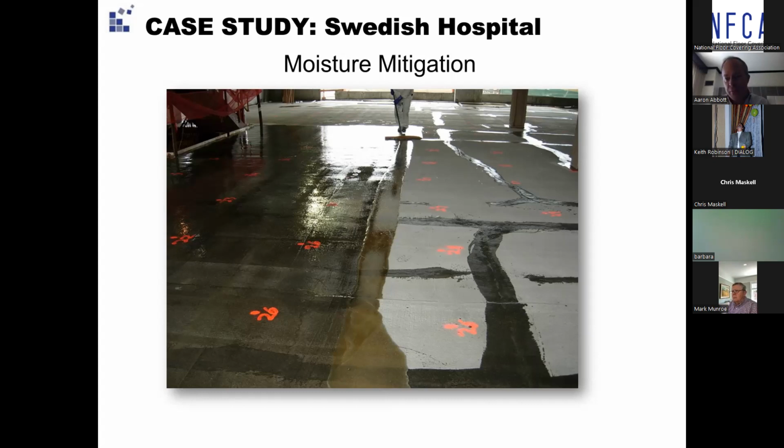You know, it's not cheap to put this stuff down. You need the blasting, and the epoxy itself is not inexpensive. But one thing that it allows, in this case, it allowed for sort of an insurance policy that by the time the floor covering was going to be installed, if you use this stuff, there's going to be no need for worrying about whether or not the concrete slab is going to be dry enough to install. So this kind of takes that out of the equation, takes the maximum RH tests out of the equation. It mitigates it. These things have very, very low permeance.